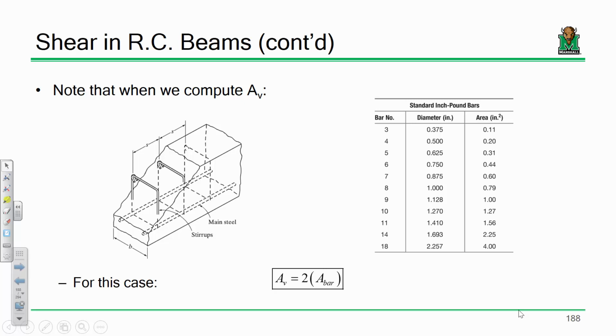So in this image, I don't have 4 stirrups across a crack, I have 2. But the thing to keep in mind is that across the crack, I'm not going through 1 bar, I'm going through 2 per stirrup. Same thing here, I'd be going through a bar here and a bar here. What we have in this image are sometimes called either hoop stirrups or U-shaped stirrups, like I drew right here on the board.